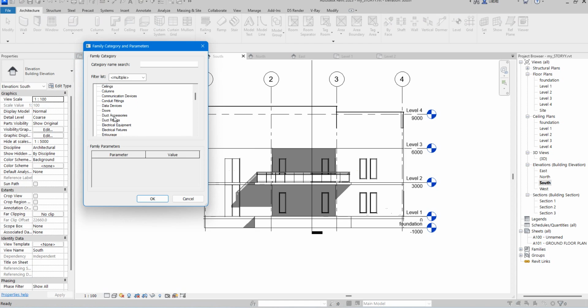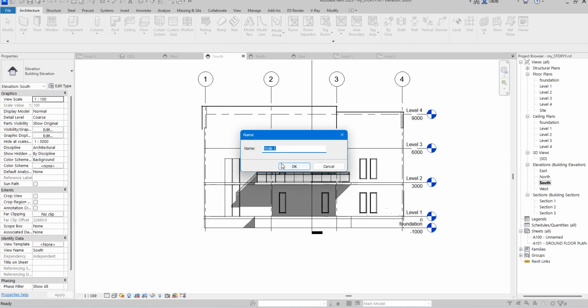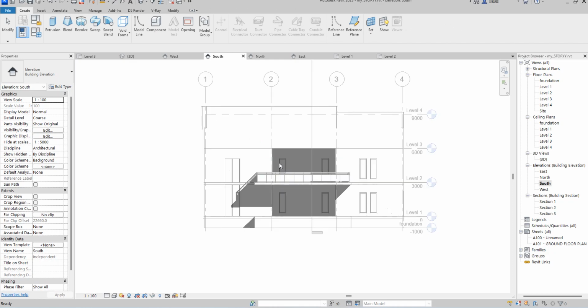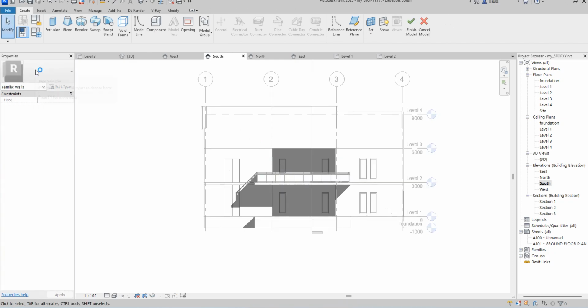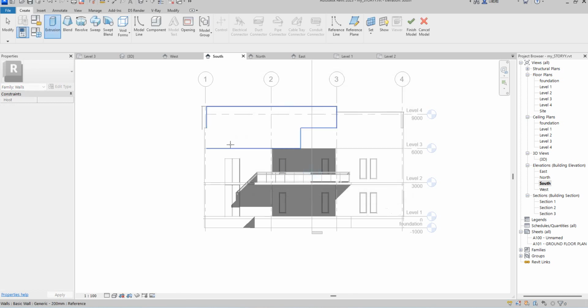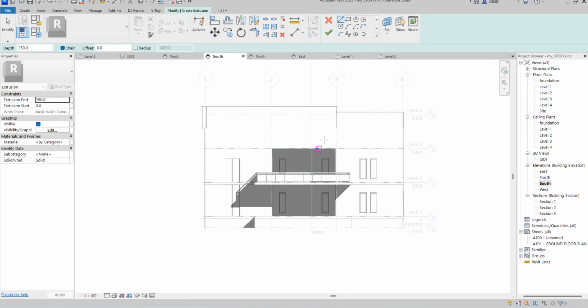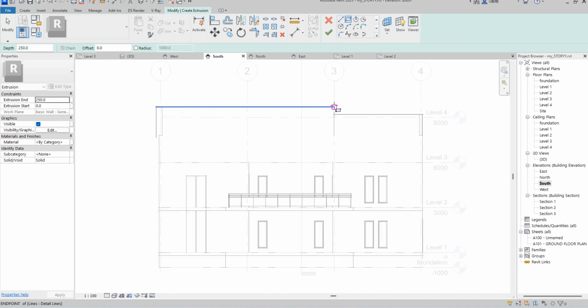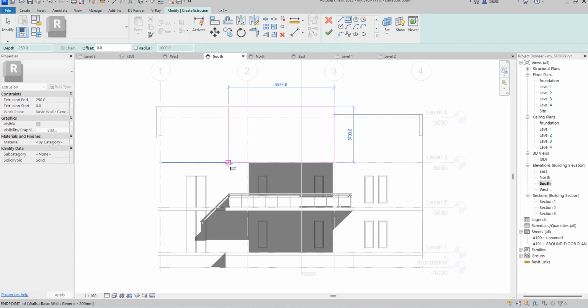It depends on you. You can come here and use wall. So you're working with wall. I'm going to use this one and say okay. Wall. So here is what I'm going to use mostly on this elevation. The first thing I need to do is I'm going to work mostly with extrusion completely. So I will say extrusion, say plane references. I will select a plane here. I'm going to face this one squarely first. So select this one, now put the massing front here.